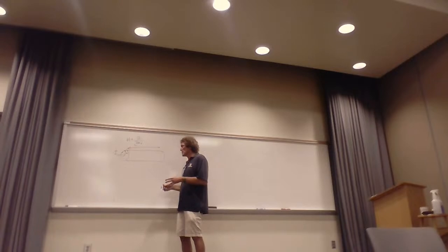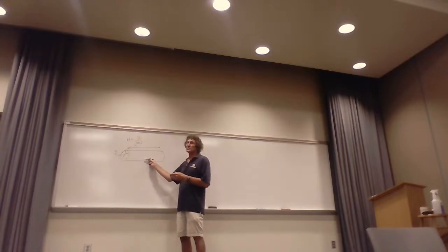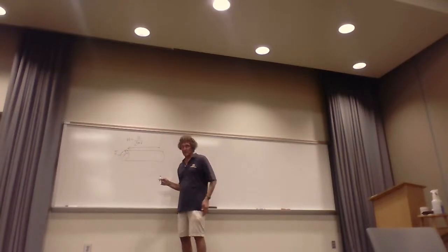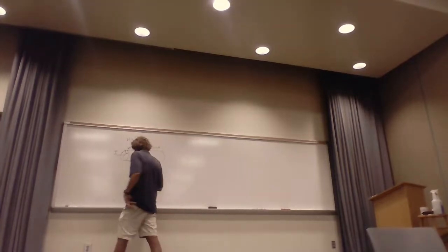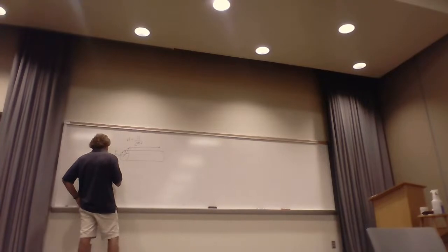That r distance. So I don't even bother with that. I'm just going to tell you this. The H field inside the wire is associated with the internal inductance. And the H field external to the wire is associated with the external inductance. Do y'all follow me? Now the internal inductance, we got that. So if we talk about internal inductance,